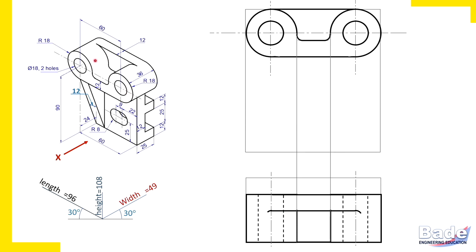The curved surface is not 36 mm. It is 36 minus 12. That is why this portion is to be erased. Remember this, two visible edges intersecting suggests some correction. And remember, when there is a joint on the boundary generator of a cylinder, if a joint appears, then the boundary of the cylinder inside the joint is to be erased.